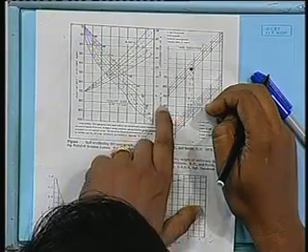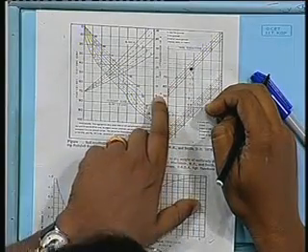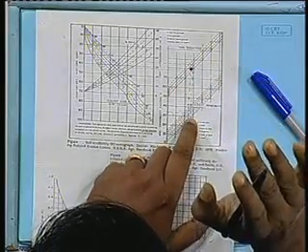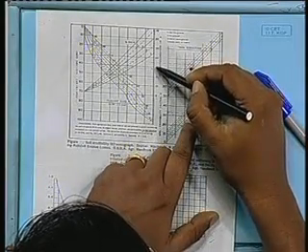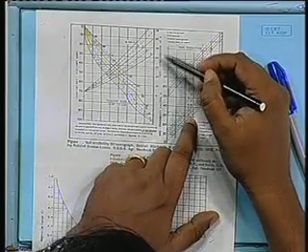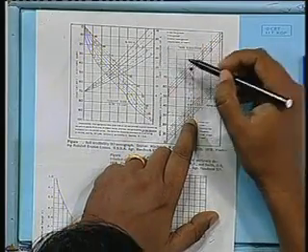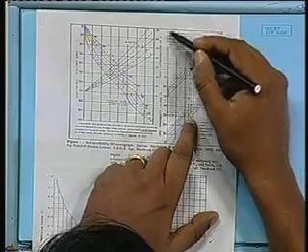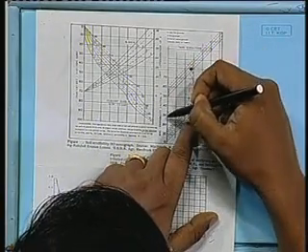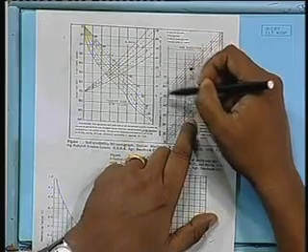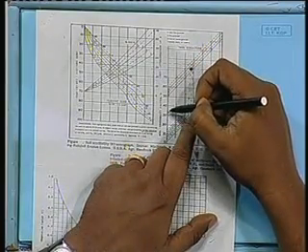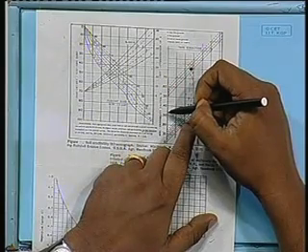So we find out the soil permeability and soil erodibility factor K. Let me explain this first. The value that we got, 0.3, is the first approximation of factor K. That can be further corrected with the use of the structure and the permeability. Whatever value we get after that would be close to this 0.3, but somewhat different. It may be 0.29 or 0.31.